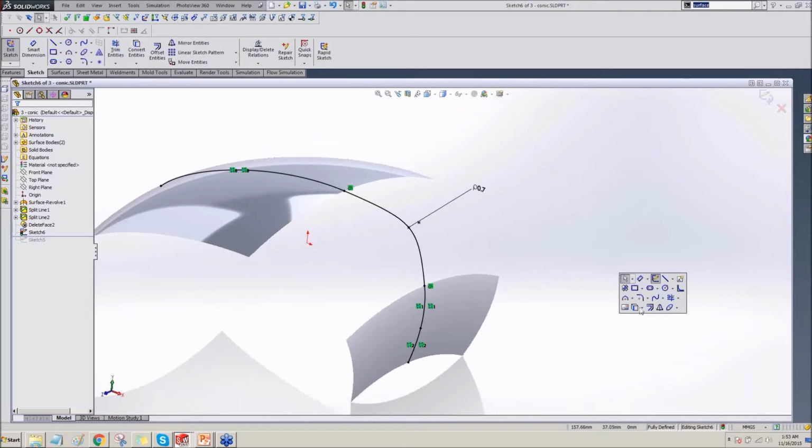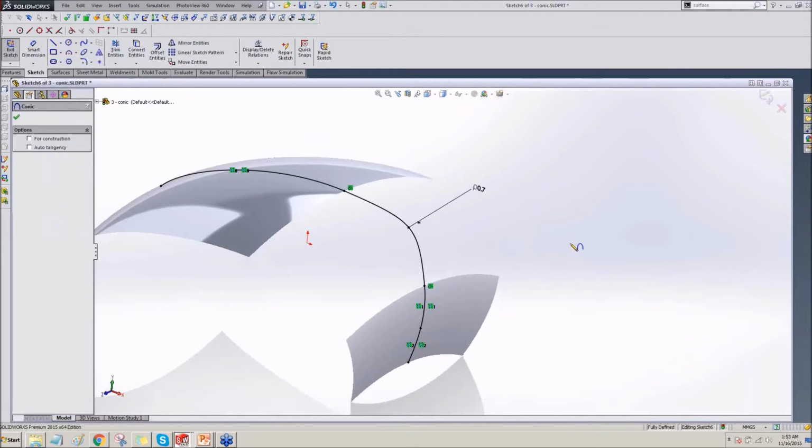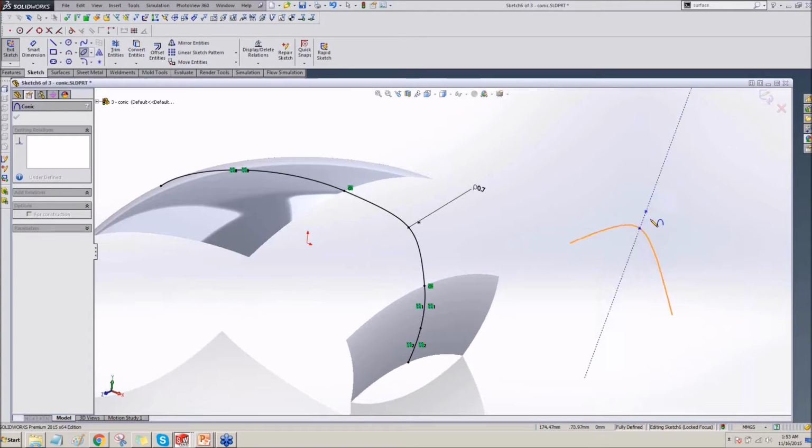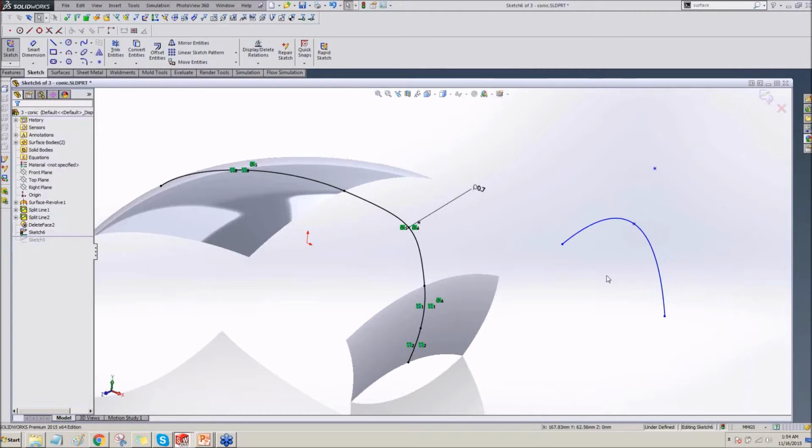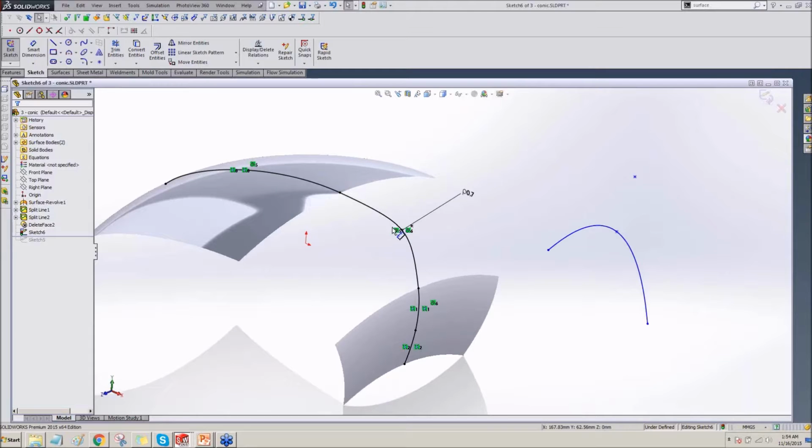Now, if I were to create a freestanding conic here, for example, somewhere like this, I have the option to actually make a symmetrical conic. Here you can see that it's not symmetrical, but if I need it symmetrical, I can just move to the middle and SolidWorks will generate an intersection line for me to set the symmetrical conic. So this is what a conic is all about.